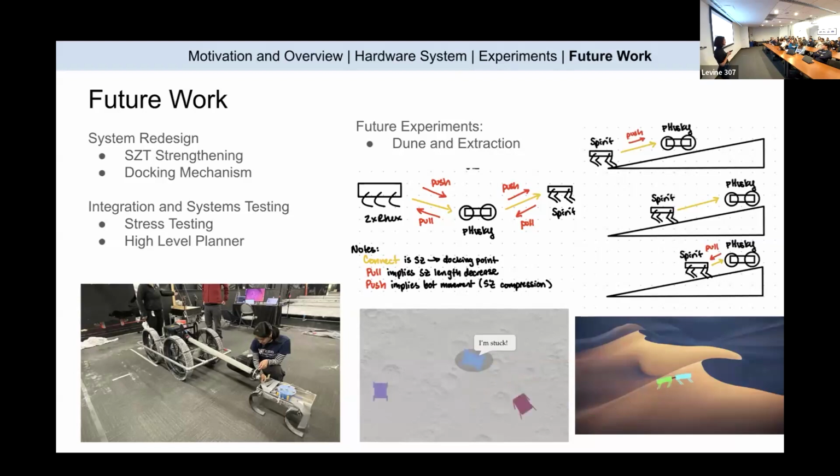What type of locomotion was the best that you tested for this environment? You tested legs, wheels, and I don't know what the Rex legs are called, but other types of legs. We did not test Rex on our own with the C-shaped legs, as it was the tripod gait. That's something we will be doing in the future, but at least compared to the wheeled rover and the Spirit that we did have on site by the time November came around, the legs were definitely better for just getting around and not getting stuck. One of the things we did find is that should you spin your wheels continuously, you'll compact the dirt more and more, and then you dig yourself a hole because it keeps that trench. There's no way of getting back out because all the material is just gone.